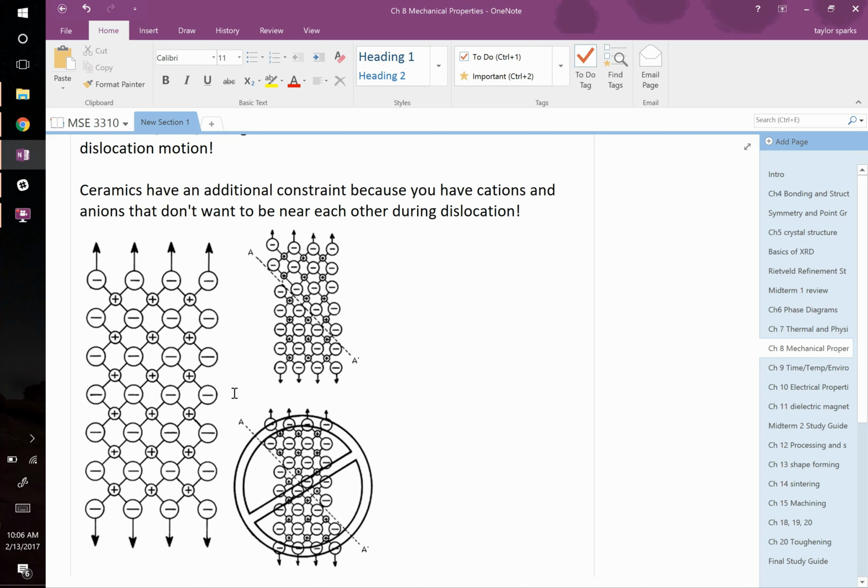So, you've got a ceramic, right? You can imagine a densely packed plane, probably along this plane, and a densely packed direction, like that direction. Why can't these things slide past each other? Well, the problem is, even if you do identify a slip plane, why don't they slide past one another in ceramics? Anybody have an idea? Be a good guess. Actually, they can. You can have a really symmetric structure, like rock salt. Rock salt's super high symmetry. You're going to get a ton of really high density planes. From a slip system perspective, you'd think, hey, this should be slipping.